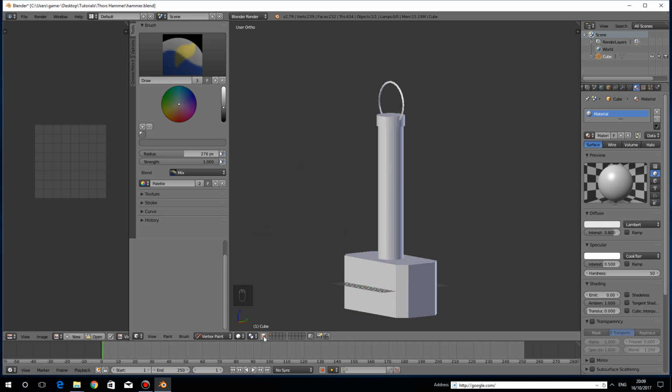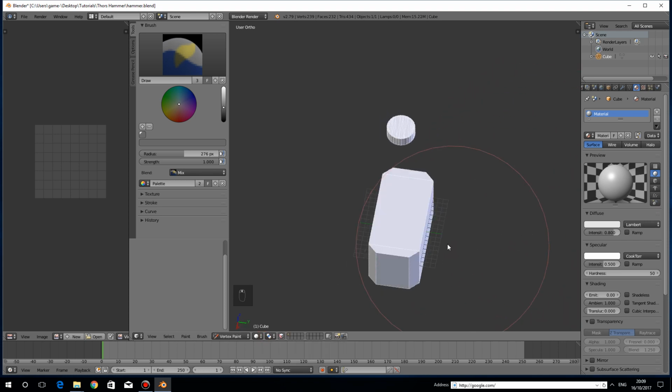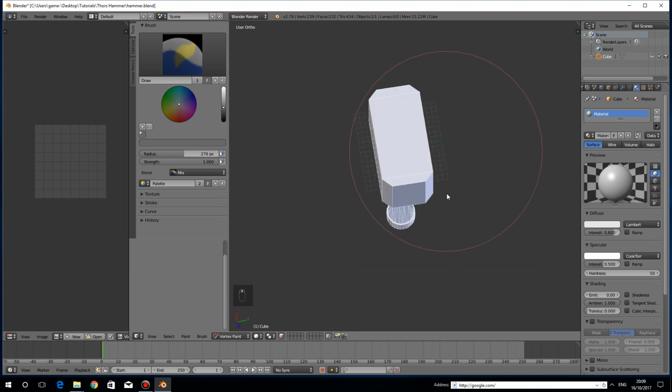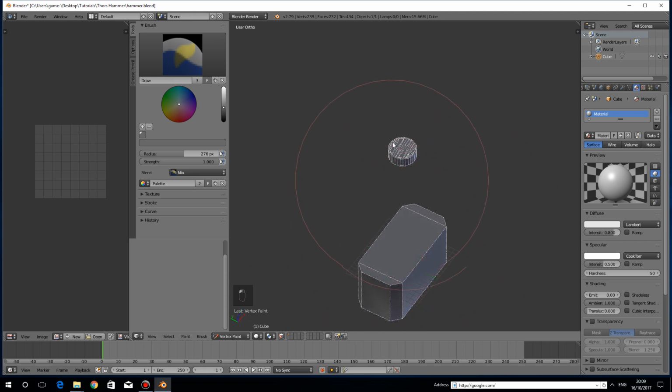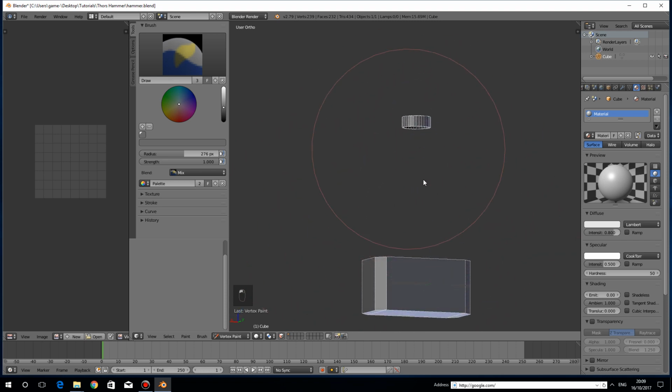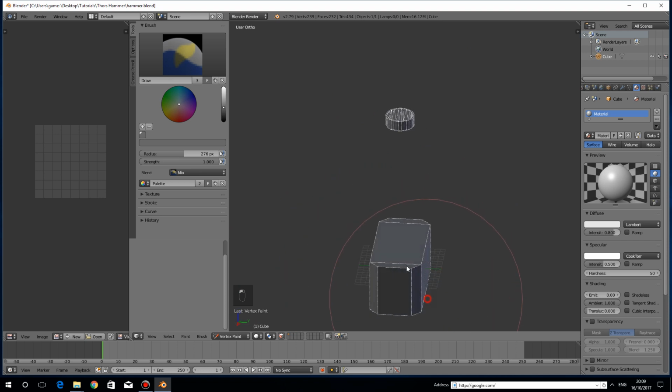I've forgotten this little button here. This is face selection masking for painting. If you click this, there you go. You've only got your selected faces, so when you paint, you only paint the selected faces. There we go, my mistake. See, we're all human, we all make mistakes. There we go, and then underneath, paint everything. Just make sure you've got everything on there.